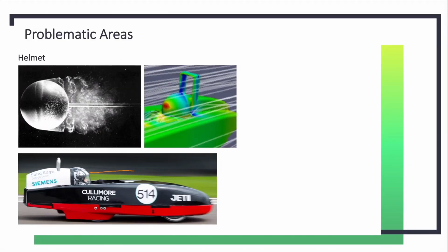One way we can deal with that is to create a fairing from the helmet. And what that does is to promote flow attachment off the helmet and continue it rearwards so we can have really good control of that wake. So now, if we have a look at it, the airflow will hit the front of the helmet, travel round, continue to be attached onto that fairing and down into the wake.